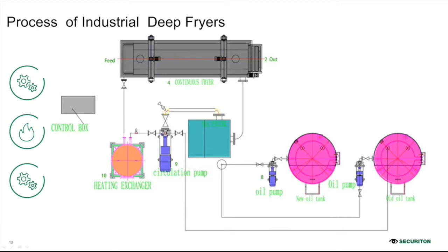At the same time, the working oil will be filtered through the oil filter, and the heating circulation pump intermittently draws oil from the working oil tank to replenish the working oil. So this is the whole working process, and we need to mention that the heated, high temperature oil will be circulating back and forth to the filter and to the unit.